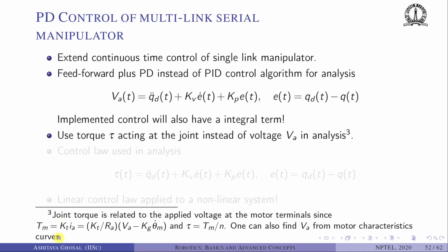Is this very serious? No. Why? Because the torque is related to the current: Tm is Kt times Ia. This current is related to the voltage applied, with a back EMF. Nevertheless, we can think of voltage and torque as related. We can also obtain this voltage from the motor characteristics, the torque speed curves, where for every voltage there is a certain torque at a different speed. So for the sake of simplicity, we will assume that we are inputting torque, not voltage.